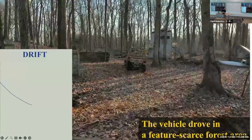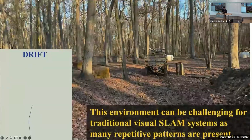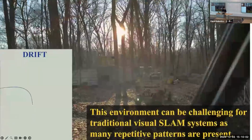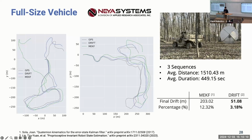So now let's take a look at some results. This is one of the military full-size vehicles that we collected data on in Pittsburgh. The vehicle has an IMU and a shaft encoder on board, and those are the only two sensors that we're using to do state estimation. This is the result of it. The blue line is the result of DRIFT. The green line is the result of an error-state Kalman filter that does not use any symmetry properties. And you can see qualitatively and quantitatively, DRIFT has better performance compared to the non-symmetry-preserving state estimation algorithms.